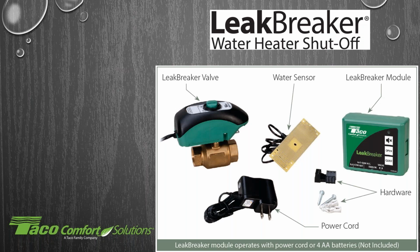So what does the leak breaker look like? We have a 3/4 inch full port ball valve with a CV of 27, meaning a very high CV value, very high flow rate, and very low pressure drop going through that valve. It does come with the sensor itself, with a 10-foot wire to the controller.